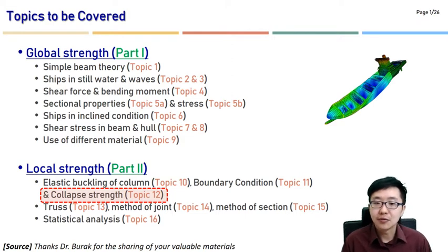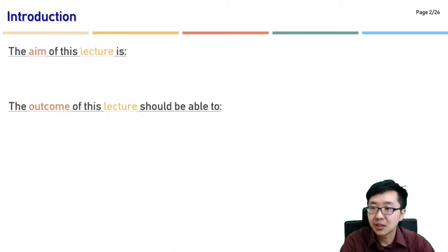And last time you remember the effective length concept and how we're going to utilize the Euler buckling equations, how we're going to calculate it, how we're going to derive all the formulations. Today it will be more practical: how shipyard and designer engineers utilize the design formulations as well as the empirical formulas, something like that.